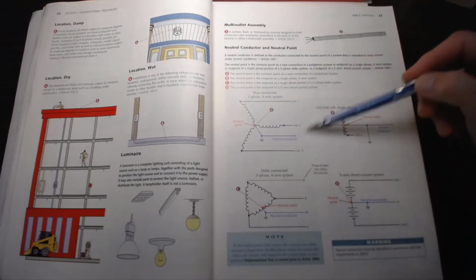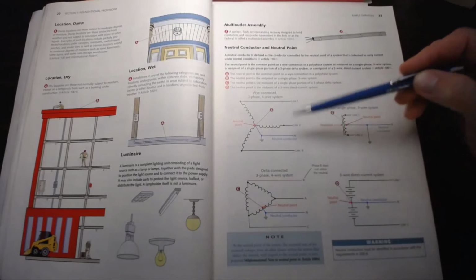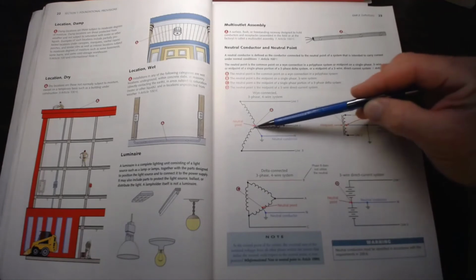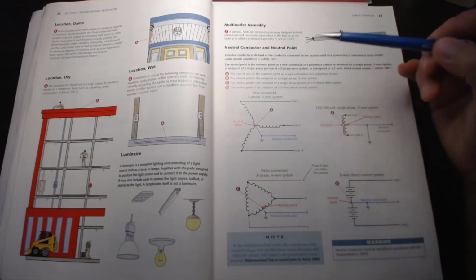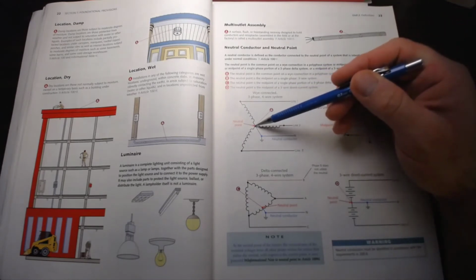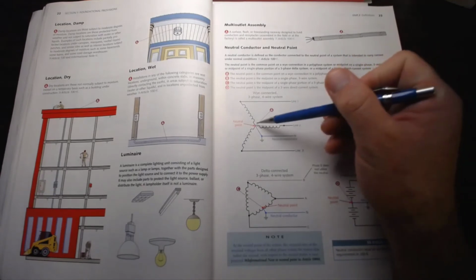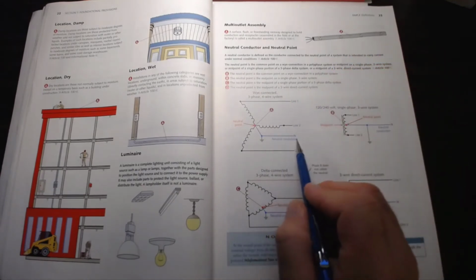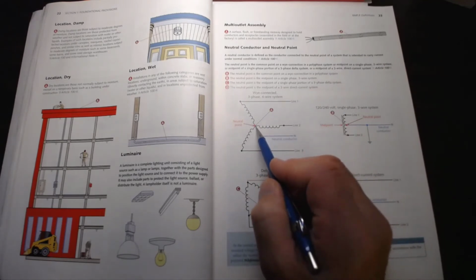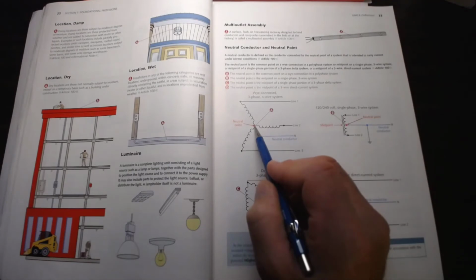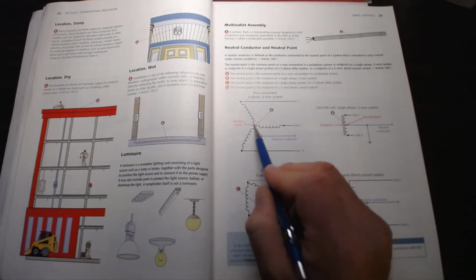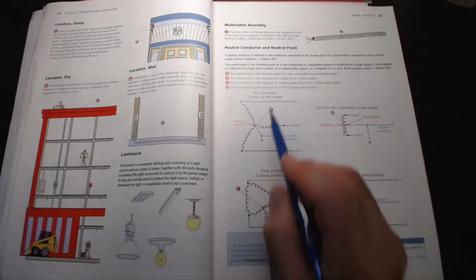And if you're not familiar with these schematics down here, this is a Y connected transformer. So these are the windings connected at a center point, which is the neutral point. And this is a 3-phase 4-wire system, the 4th wire denoting that there's a connection to the center, and that neutral point then goes out and feeds a neutral conductor, which is also grounded. So we have to ground the neutral point whenever you're using the neutral, for fault current return and voltage stabilization. So that's a 3-phase 4-wire Y connected.